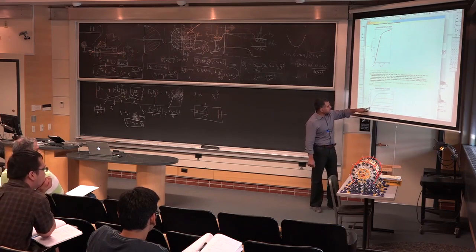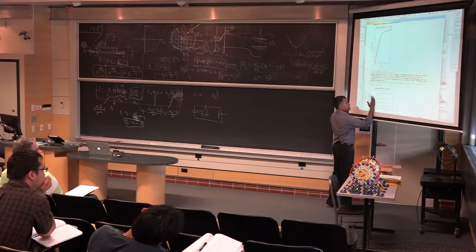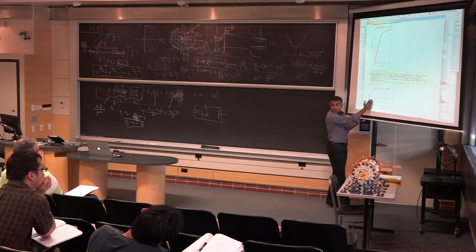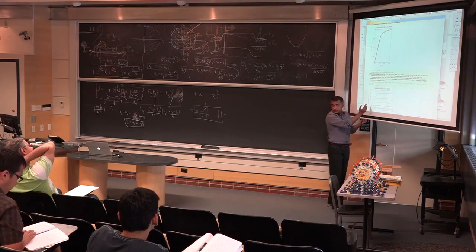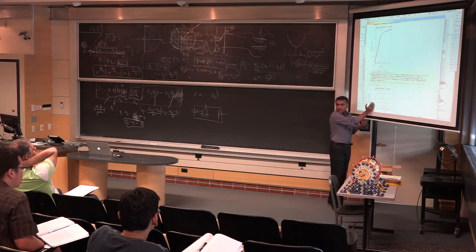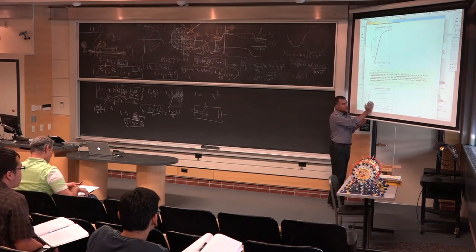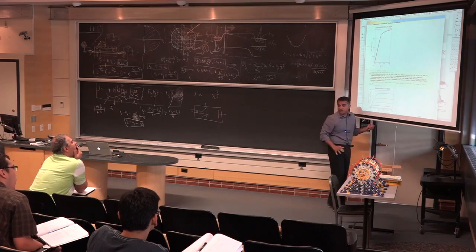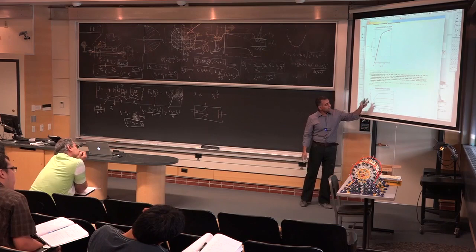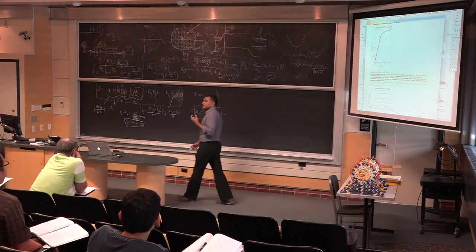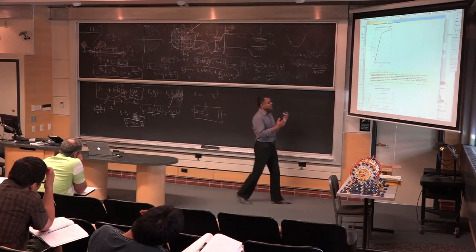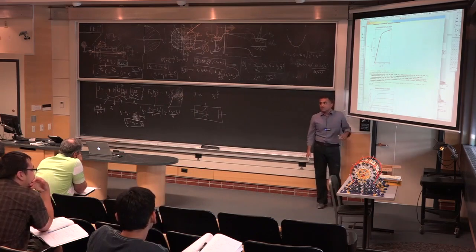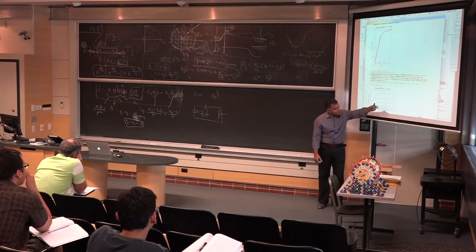But very importantly, the current increases initially. If you were just looking at this part on the left, it looks like a resistor, right? IV curve. It's a resistor. That part of the transistor, as far as gain and switching and amplification goes, is completely useless. It has some other uses, but not in an amplification and gain picture. All that business happens here. The current must saturate, otherwise there's a big problem for you. And interestingly, before people thought of the transistor as a quantum mechanical object, they thought that once you put in all the quantum mechanics, there'll be all sorts of interference and we'll get oscillations in voltage and all that. None of that happened. It's just straight-on saturation.